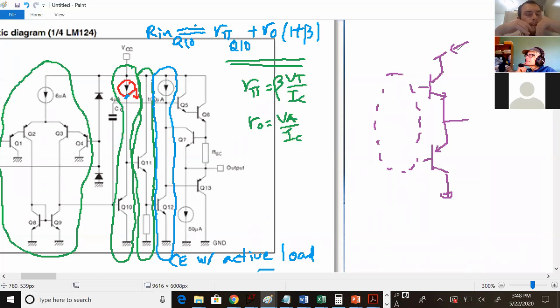Oh, and I think with the push-pull, you need a 2 VBE on difference. So I wonder if the Darlington pair maybe creates that for Q13. I think the Darlington pair is like the upper side of the push-pull. It's like the top resistor of the push-pull. Or top transistor, excuse me.